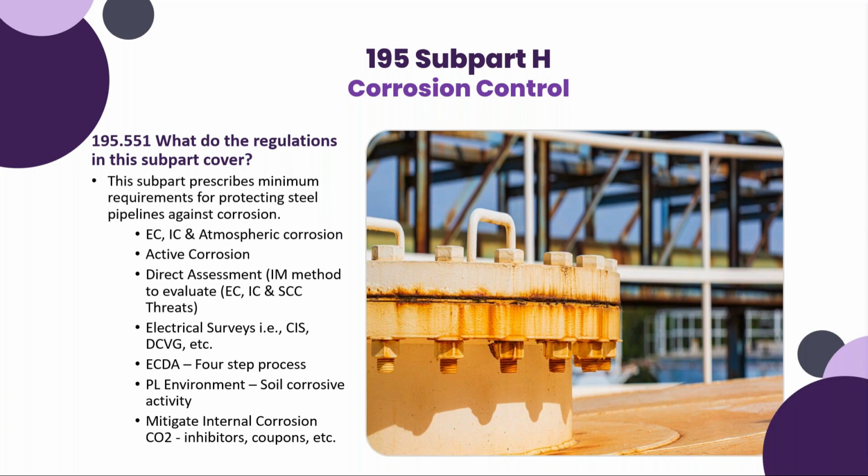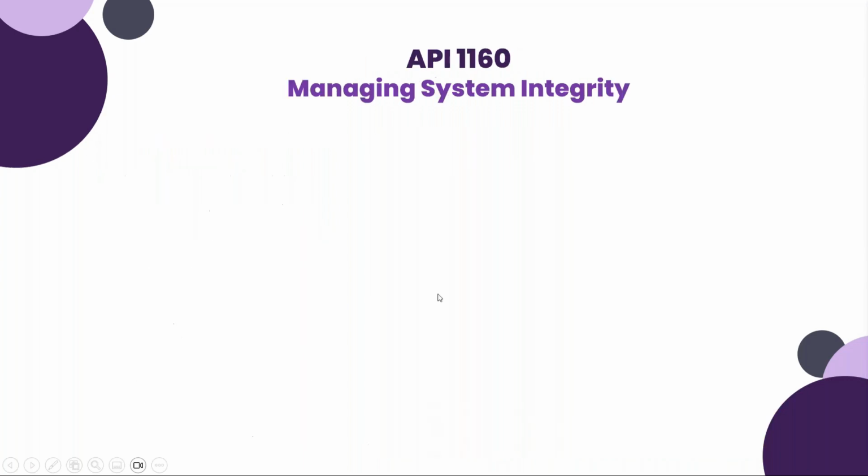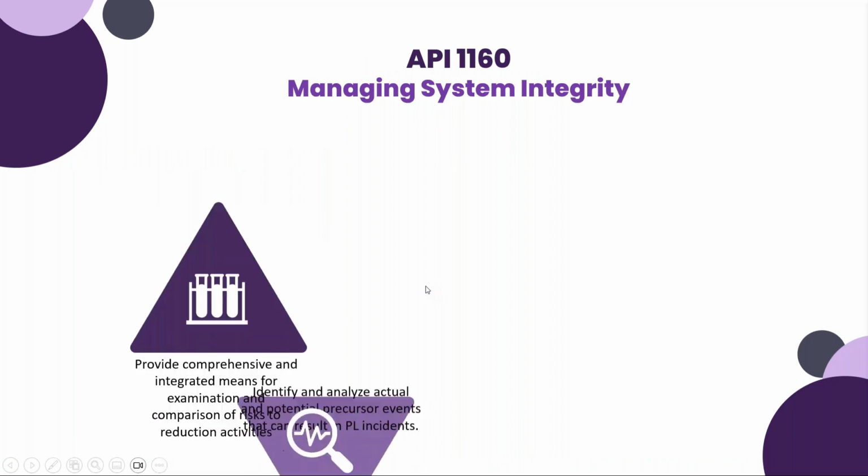You get some very low soil resistivities, and all of a sudden, you could have both AC and DC corrosion very quickly. And then the mitigation of internal corrosion, CO2 inhibitors, coupons, and so on and so forth. And biocides, of course.